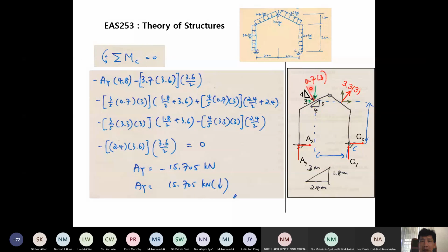So when you want to find the component for the equivalent load of this distributed load here, then we need to make use of this triangle where the horizontal distance now becomes 3, vertical becomes 4, instead of horizontal 4, vertical 3. Because this is for the inclination of this member. What we need is the inclination of the force.